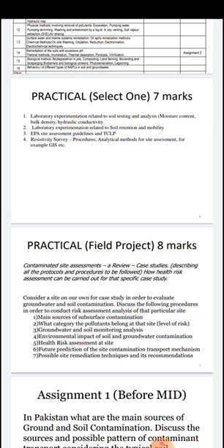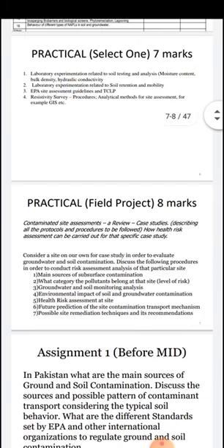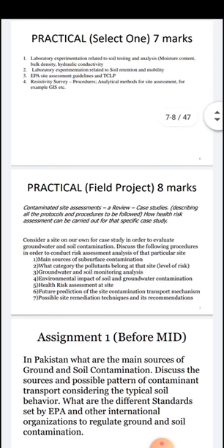Or in some cases the whole structure of the landfill can be affected by some earthquake activity, because it is going to destabilize the structure, and once the structure is destabilized, it is going to have some cracks, and it will facilitate the leakage of the contaminant from the landfill, and it will ultimately join the soil, and from the soil, it will again move forward to the groundwater.